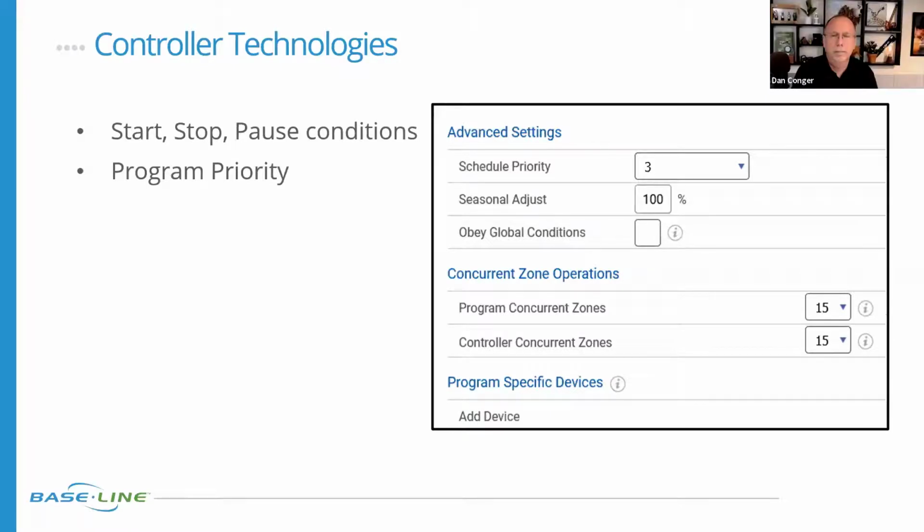So in that previous example with the park, if they wanted to keep the pitches or the playing surfaces greener or healthier than the surrounding area, if it was hydraulically designed so it was possible to irrigate the playing surface separately from the surrounding area, then they could prioritize the playing surface and have that budget be allocated to the playing surfaces and then let the surrounding area go into drought stress.